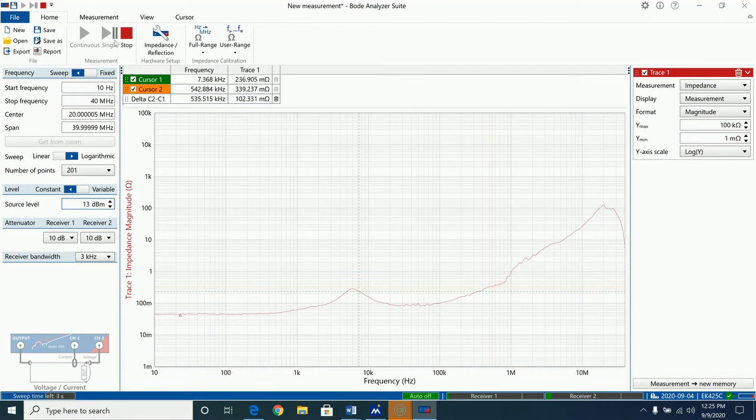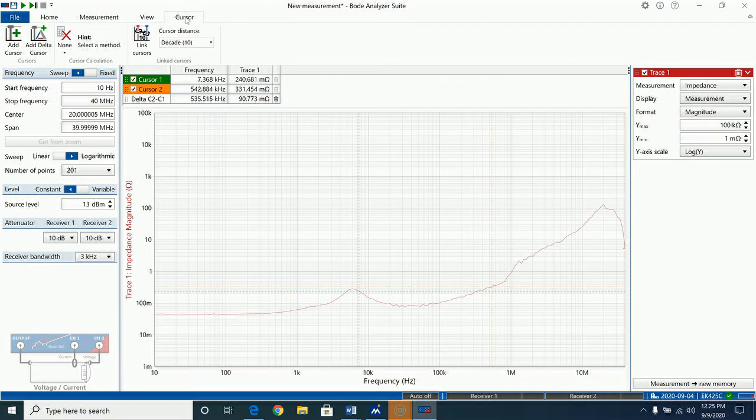Okay, so I'm going to go ahead and stop and just do one single sweep. Okay, so here we have the single sweep. Now what we can do is use the cursor, and this little hump that you see right there, that peak, that is the crossover frequency of your bandwidth. And that bandwidth is 6.06 kilohertz. Okay, so that's very important.